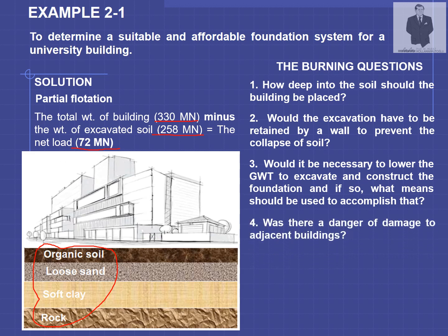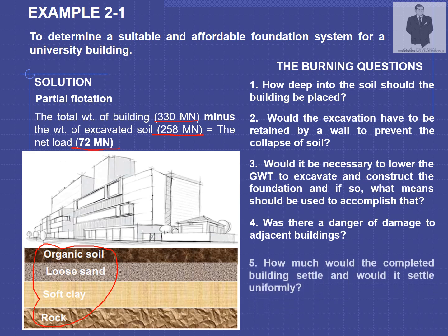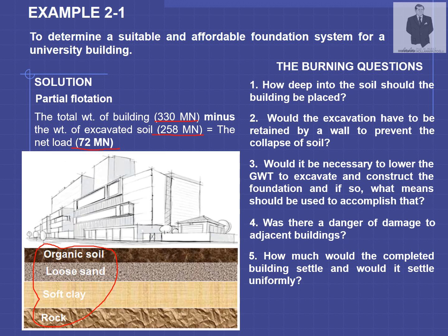Fourth question, was there a danger of damage to surrounding buildings? Due to excavation, the surrounding buildings may undergo lateral movements or differential settlements. This was another important point. The fifth question, how much would the completed building settle, and would it settle uniformly?